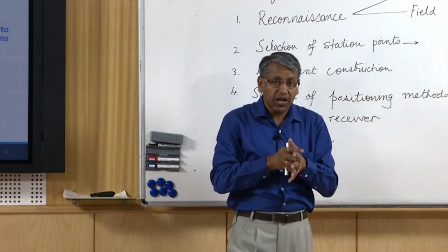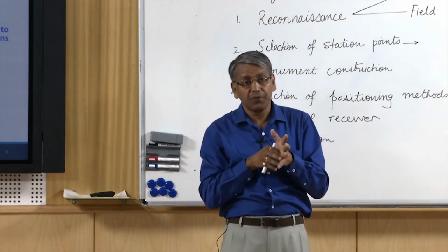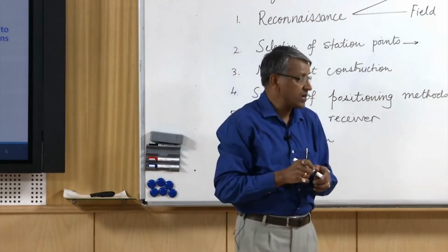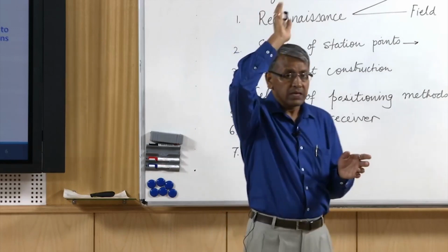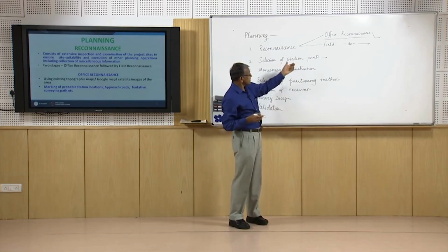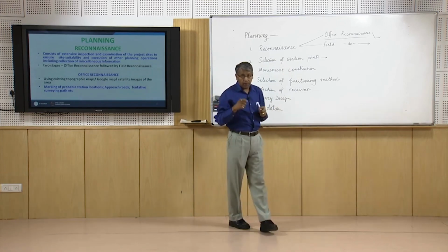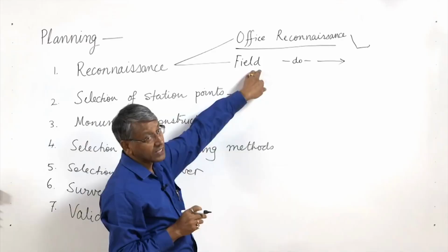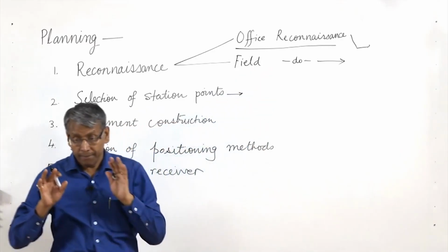We should also check, if there is any kinematic survey, whether that route is free from physical obstruction, that is, whether the sky view is clear or not.